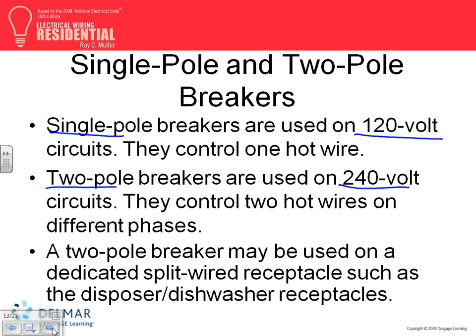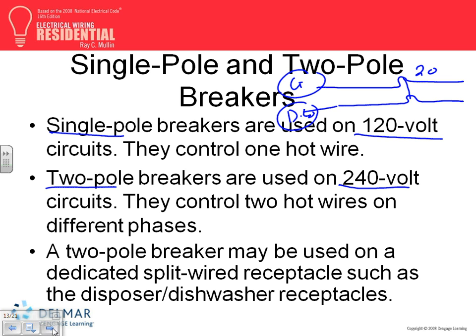But also, as you know, if we have a multi-wire circuit, do you remember what we need to do with the circuit breakers that feed the multi-wire circuit? We have to tie them together. So if I have a multi-wire circuit, here's one, here's two, tied together, 20 amp. This was my garbage disposal, this is my dishwasher. I brought one neutral and shared the neutral, right? Isn't that what we did in the kitchen? A multi-wire branch circuit feeding the garbage disposal and the dishwasher with a shared neutral. In a situation like this, guys, these will be single pole circuit breakers tied together.